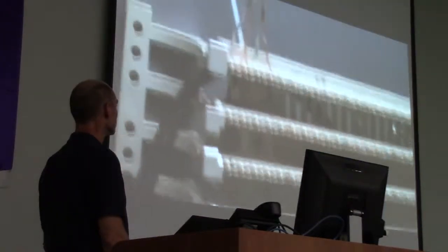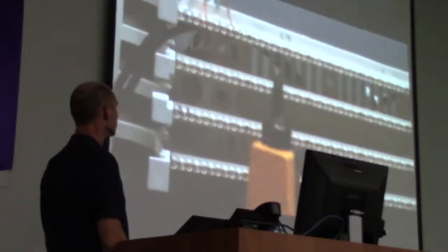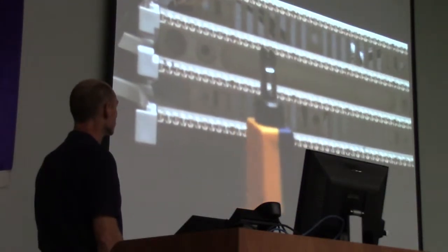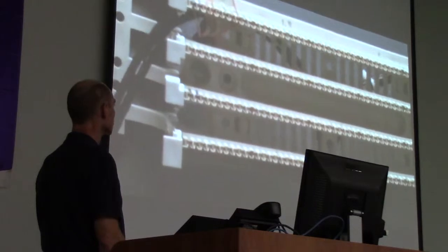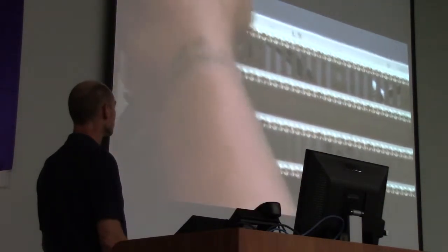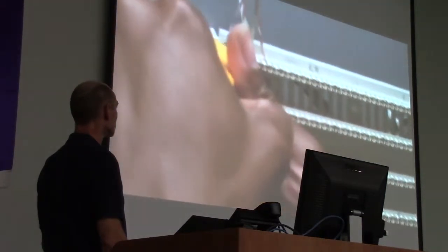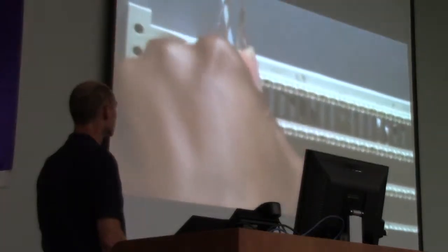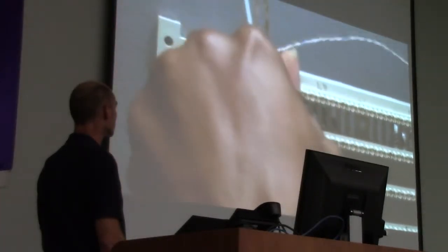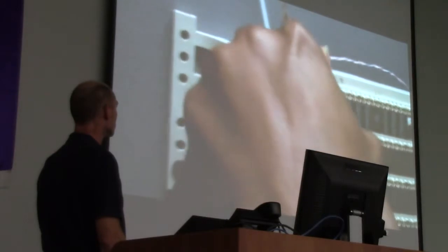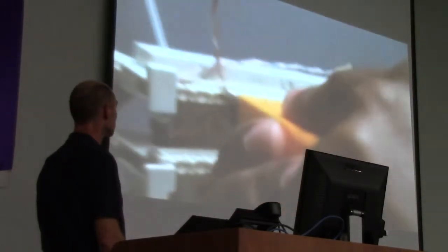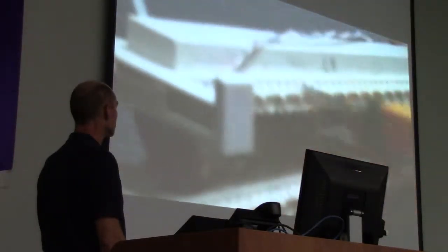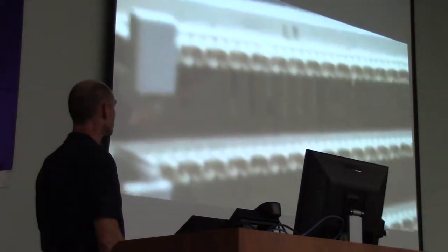All right. This is your standard punch down. This is a 110 punch down blade on here. Okay, gonna cut this with the cutting side up because the cables are facing up like so. Good blade, the cable will just fall off like that. That will be your termination.